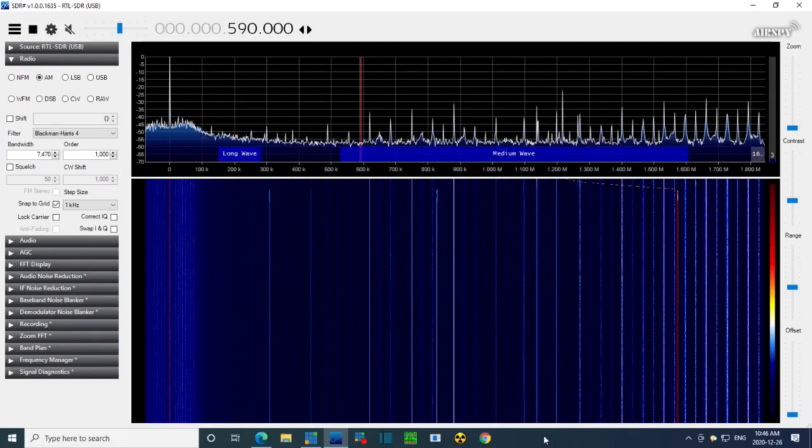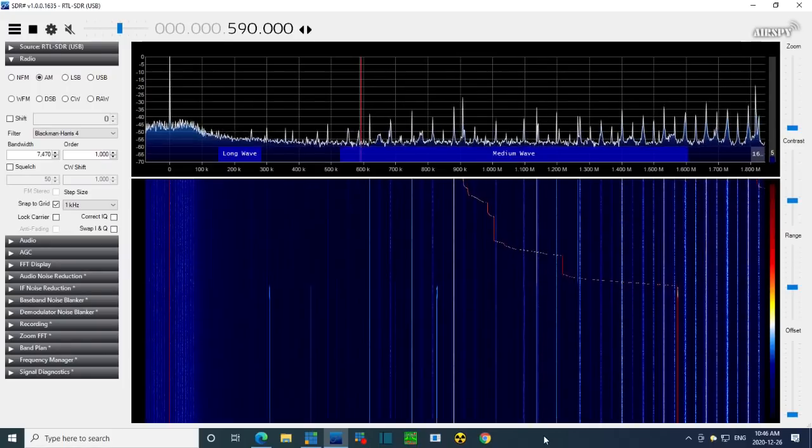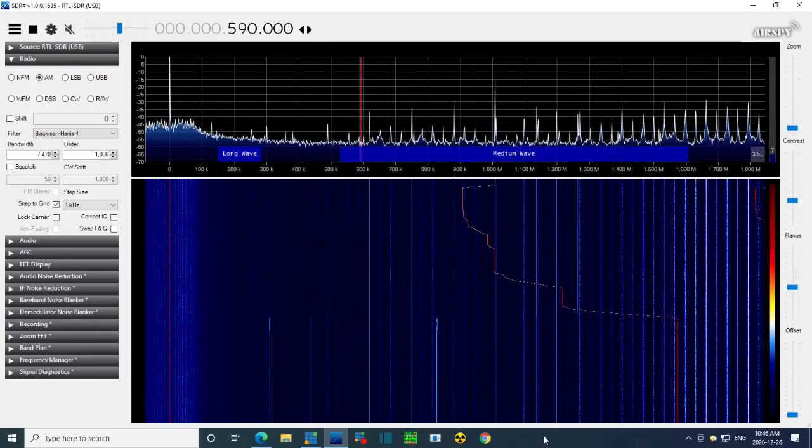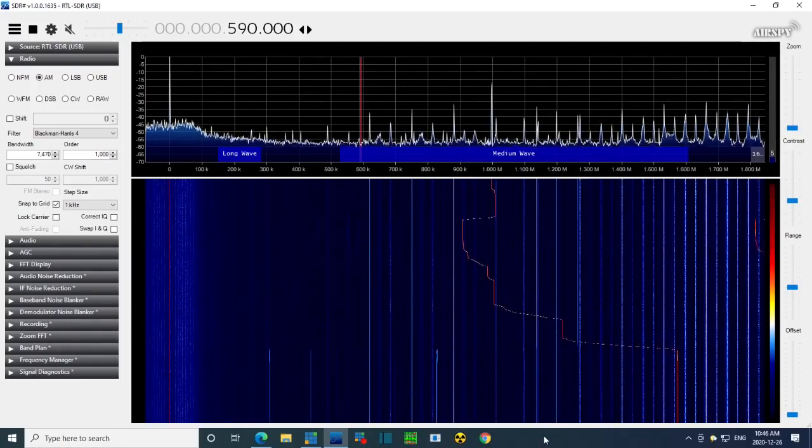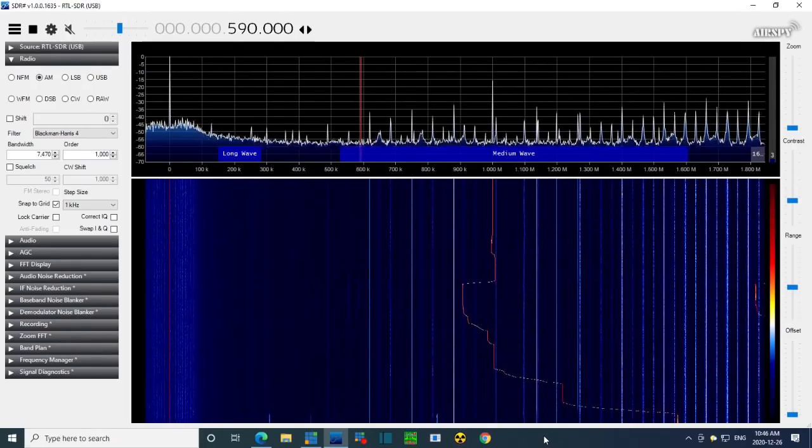Well, if we have an oscillator and we can make a signal into the radio, for instance, if I set the oscillator to 1 million here, and we think the IF frequency is 200, I fire in an 800 kilohertz signal. If the radio is working, we will hear it. Is this radio working? I'm going to find out.